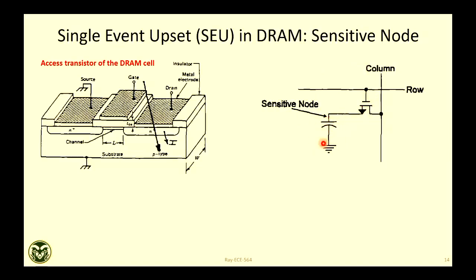So that means the charge that is stored in this is going to the MOSFET, and will it go to the bit line or will it go to ground? What is the path of this charge? The path of the charge is going to be ground, right? Because this is the path. This junction, this P region is the substrate. The substrate is connected to the ground body, right? So nothing will happen, nothing will go to this bit line.